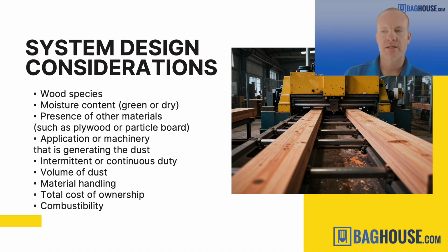Total cost of ownership is an important concept. Basically, that means more than just the upfront price tag for your system. What's the total cost over the long-term life cycle of the dust collection system? So we may spend a little more on a VFD for your fan up front, for example, which may save you energy costs over time and result in a lower cost of ownership. Things like that we want to look at. We look at the whole system in the long term to make sure that it's the best, most efficient system at the lowest total cost of ownership over time.